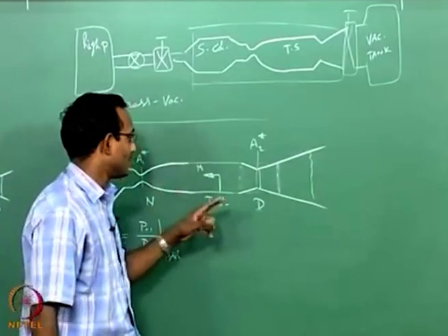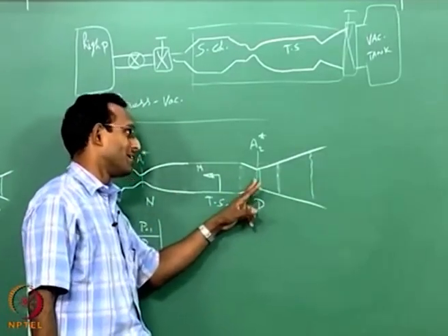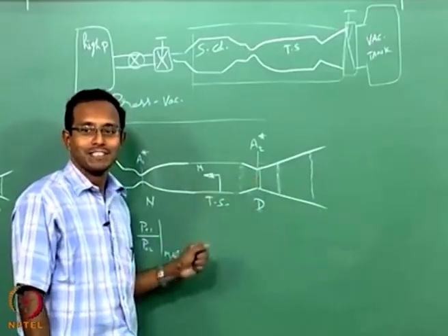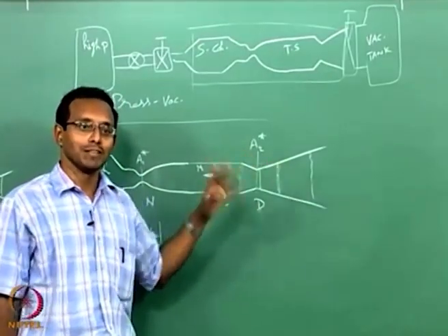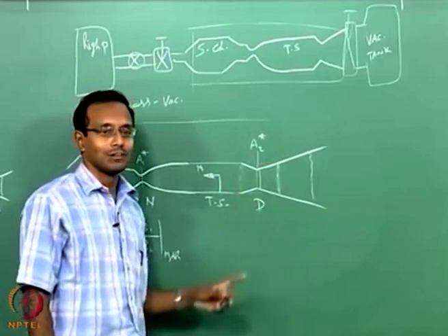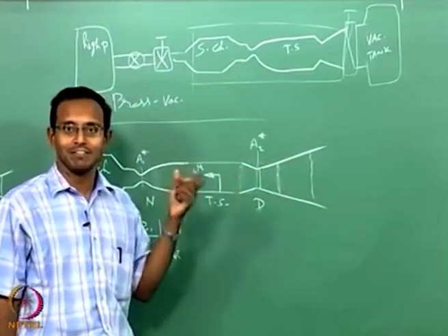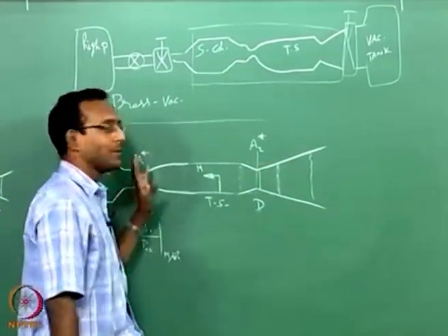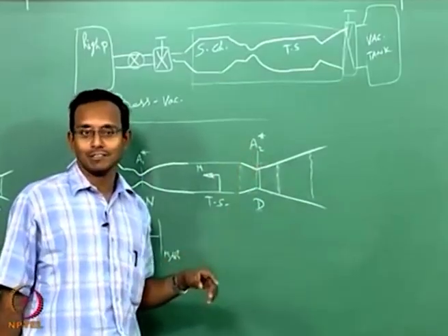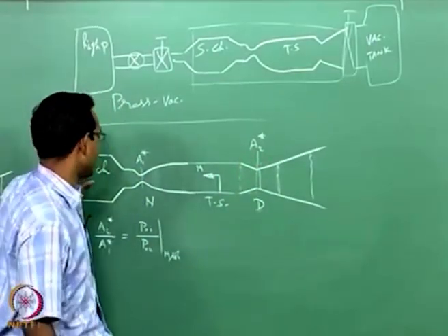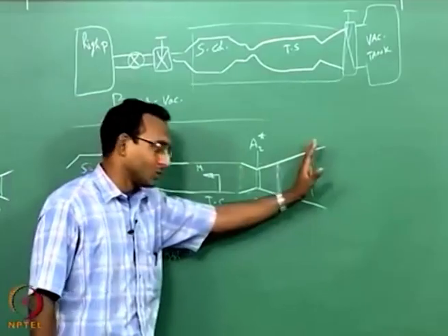So now they will think about some safe operation point where it will never jump into the test section. So they will tell that, okay, the minimum needed is this value of P naught, I will operate say 10 psi above it, something like that. They will operate at slightly more pressure than that, so that they have a safety margin somewhere. This is typically the way a supersonic tunnel works. Okay. They will keep it such that the shock starts and goes that side.